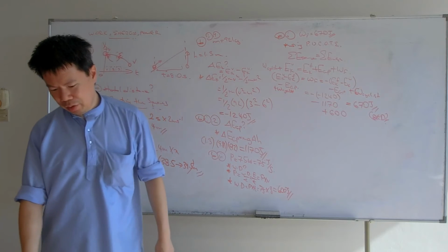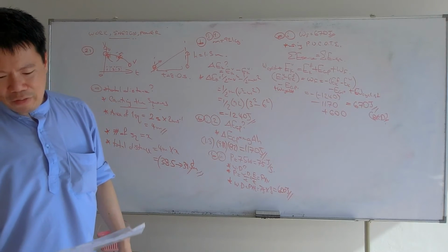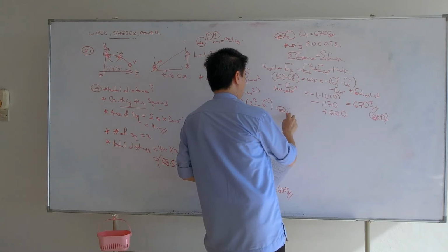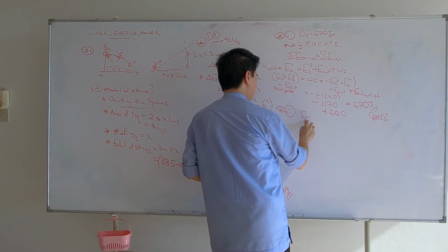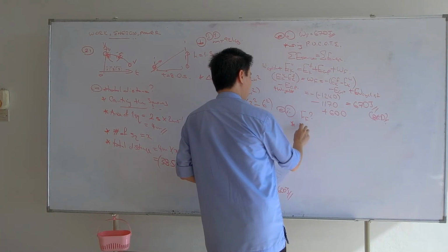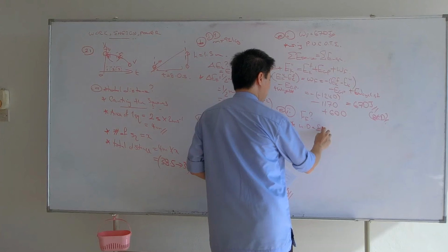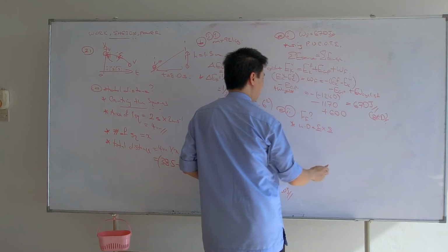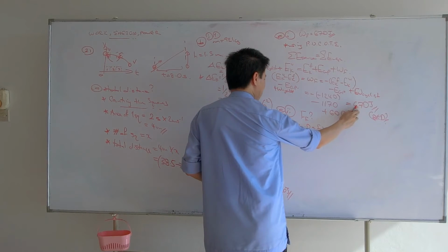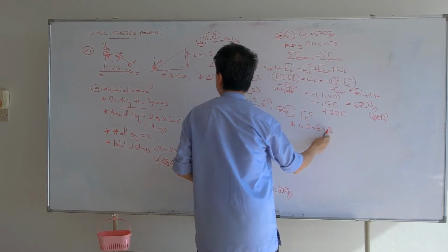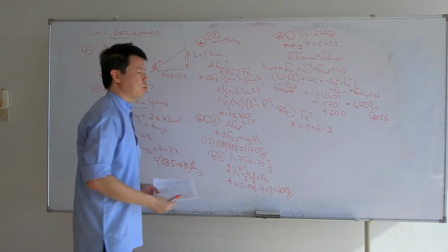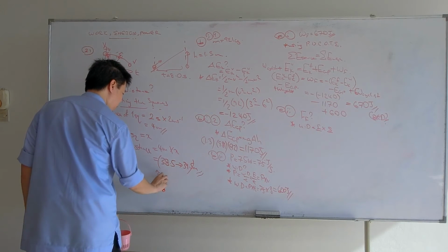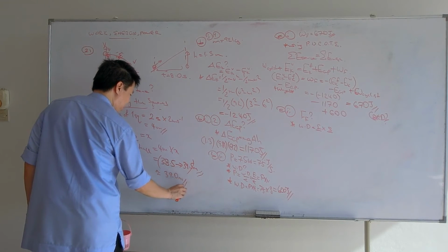Okay, so now we move on to the next component. C2, determine the average magnitude of the frictional forces. So frictional force equals, so what do we use? We use work done is equal to force times displacement. In this case, the work done by the frictional force is 670. We want to find F. Now we have a problem because we need to find x, the distance moved. In this case, we already measured here, so I'm going to choose a value of around 39 meters, just in between.